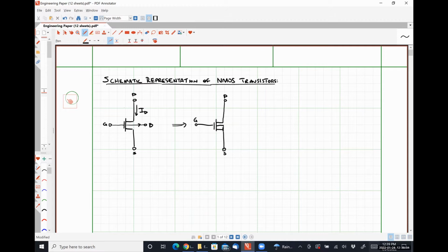Okay. This is done when we either want to or can ignore body effects and the body effect on the change in the threshold voltage. So if the body and the source are at the same potential, body effect is exactly 0. And we'll go from there. And then finally, our drain current will still be this guy here, ID.